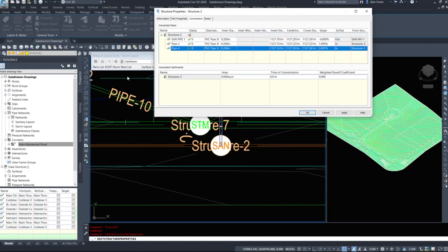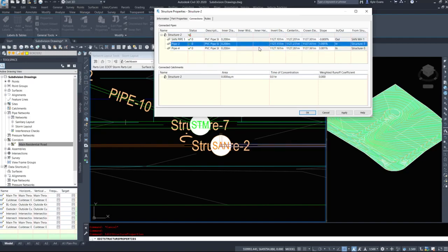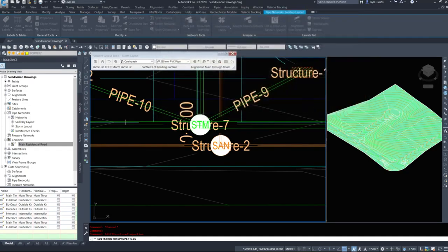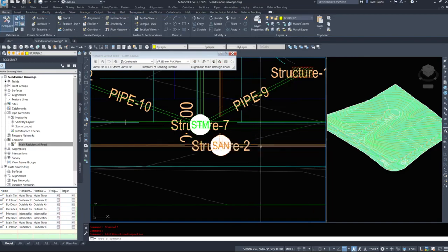If the pipe happens to come in from over where my mouse is into the manhole and out to the left, that is between 90 and 180 degrees. We need a 150 millimeter drop. So we would change this number by 0.15. So again, remember these numbers, 1127.131, 1127.161. Because when we go into the next pipe properties,